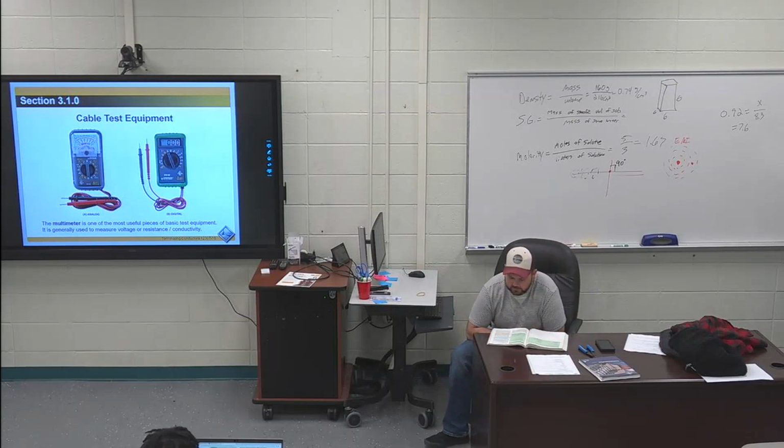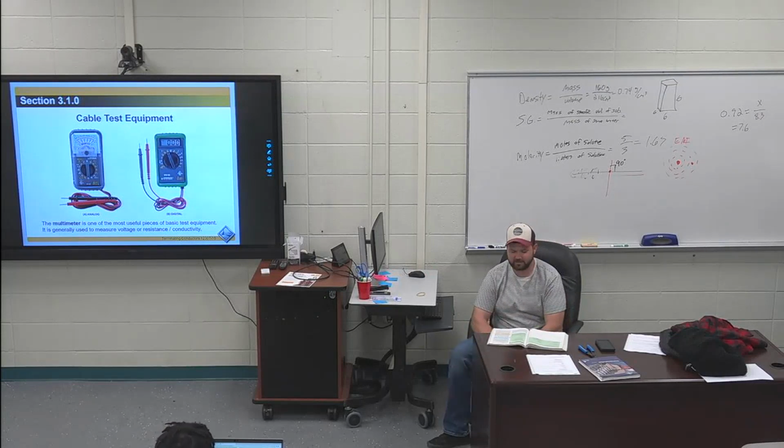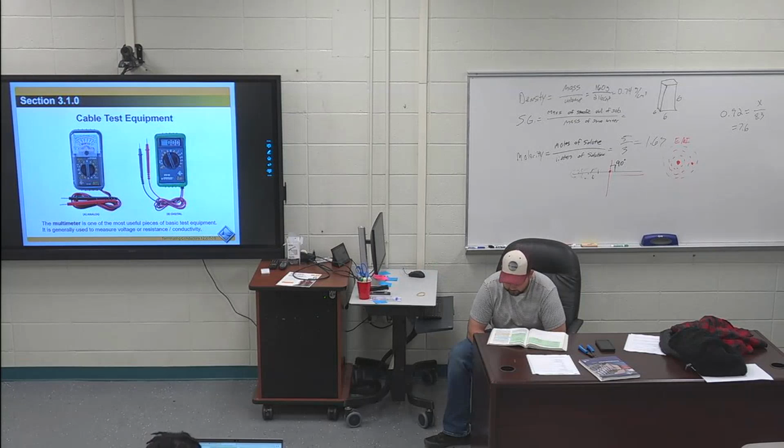Test equipment. I have telephone test set highlighted. The whole thing is highlighted. It is going to be a module review, a practice test, and an online test question out of this one bullet point. Telephone test set. The device in figure 53A is a handheld tester that connects to a phone line with alligator clip leads. It can function as a station receiver, telephone, test the operation of the subscriber service to test the premises wiring, or a continuity tester to ring out conductors.